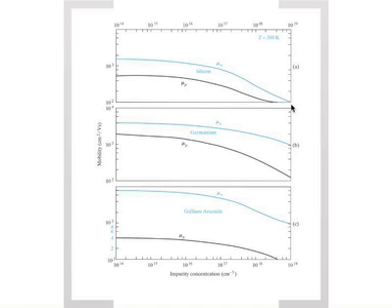Even though you are, of course, why do you dope? Why do you add impurities? Because you want more carriers, right? You want to make it more N-type, let's say, the silicon. So you're trying to get more carriers, but at the same time, you need to be aware that the mobility is dropping several orders of magnitude as well. So you need to be careful that two things are happening. You're increasing the carrier concentration, which of course can increase your current, but your mobility is dropping. So you need to find an optimum concentration that you want to work with.